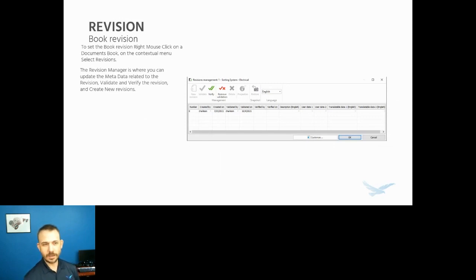And the name and initial that it puts in there is pulled from the application settings. That first page under collaboration settings, there's an option down there at the bottom for name to display. You can either do initials or you can customize it with your first name initial or however you want, right?